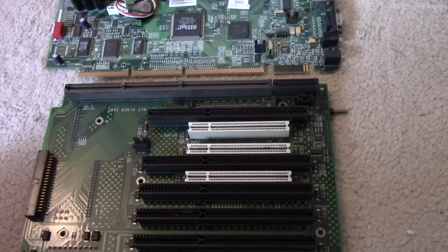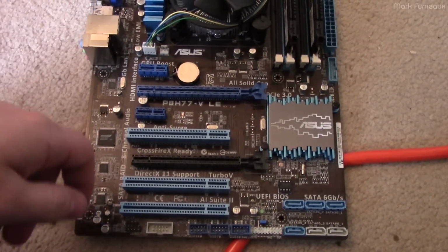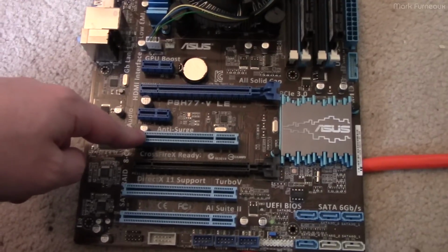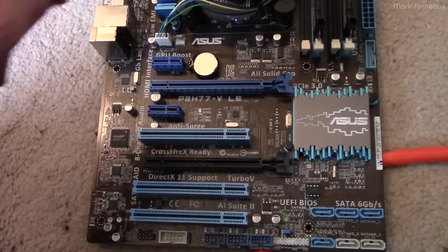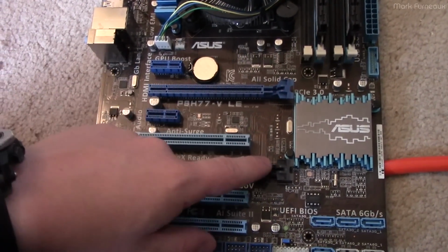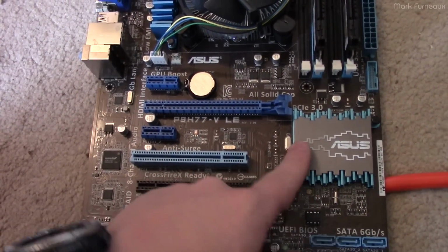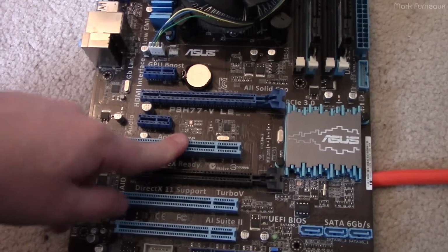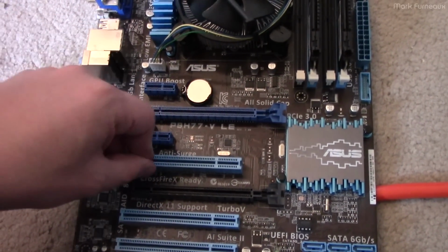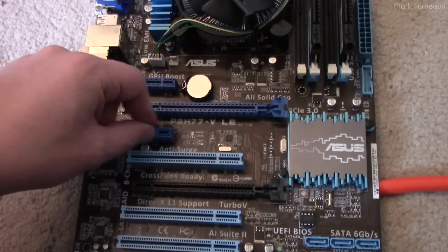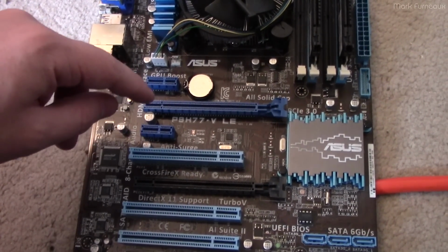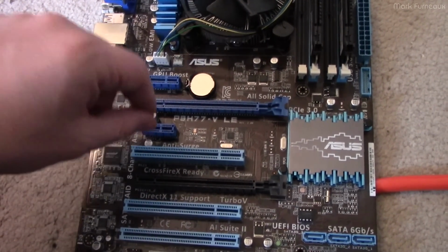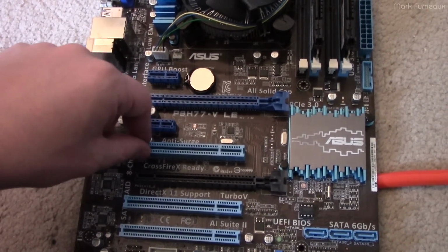In fact, let me see if I can go find one of those. So here's an old board that I have, and this has both PCI Express and PCI slots. As far as I know, this chipset does not have PCI support, so I think the chip might be under the heatsink, because they probably put it near the chipset. There is a bridge chip which creates a PCI bus and hangs it off PCI Express, which is what's natively supported by the platform. And as part of the standard, PCI Express supports these chips running PCI buses through it.